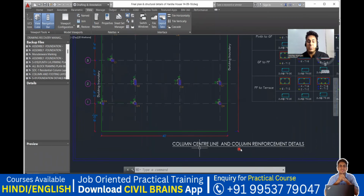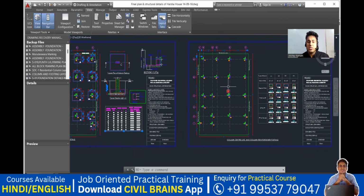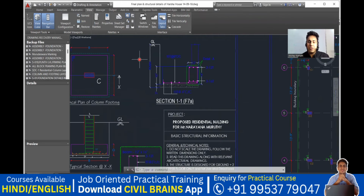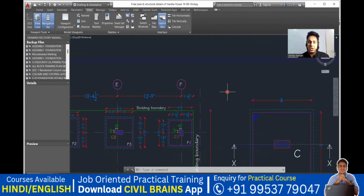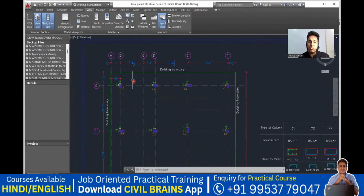So we'll see the column center line marking here. Once the footing details are understood, the next is the column details. Again, whatever grid lines you have drawn, the same thing will be drawn here. It remains the same. There won't be any changes. And one more thing, the distance between the grid lines, I'll explain it here. So how do you do all these things practically on the site? You are going to mark it.